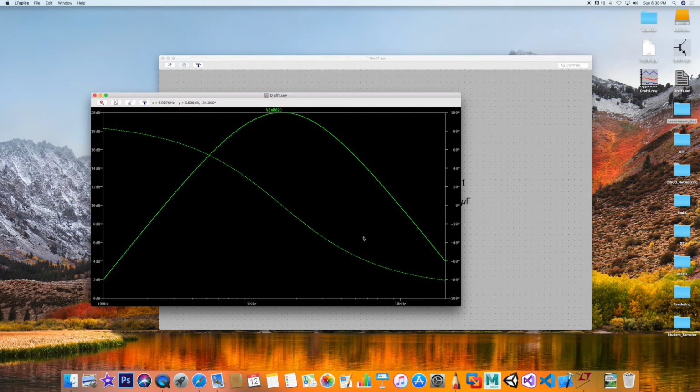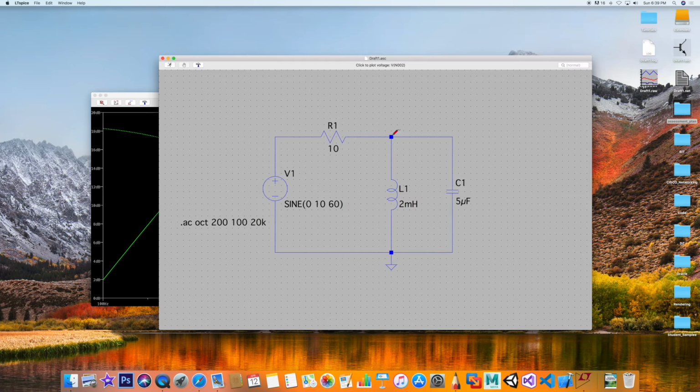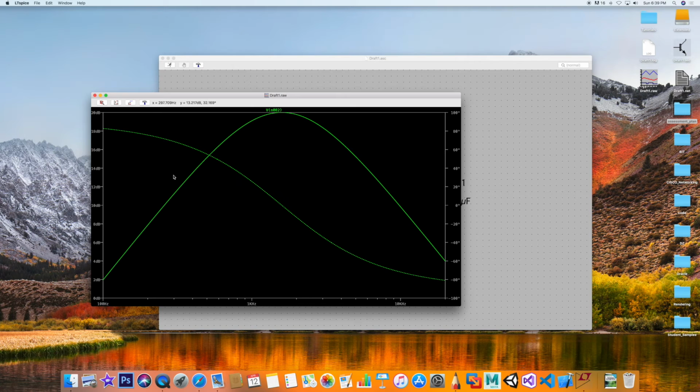I'll leave it here and observe that you're peaking at a certain frequency right here somewhere. And notice it's 1.5. Okay, it is almost the same frequency that we did with the series circuit, right? For the resonance. That is resonance right here when you're maxing out over here in terms of the impedance. Okay? And after that, it's a matter of what is your circuit doing? Is it more capacitive on this end or is it more inductive on this end? How do we know that?